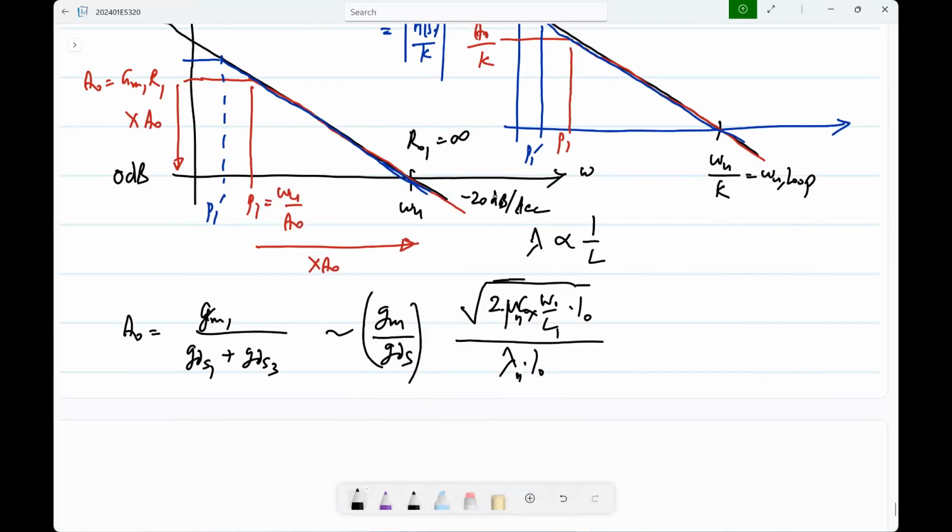Now, of course, that comes with a disadvantage. What is the disadvantage of increasing the MOS transistor length? Larger parasitic capacitors, right? All the parasitics will be larger proportionately. So that is a problem. In fact, if you increase the length to increase the DC gain, to keep the GM the same, you have to increase W also.